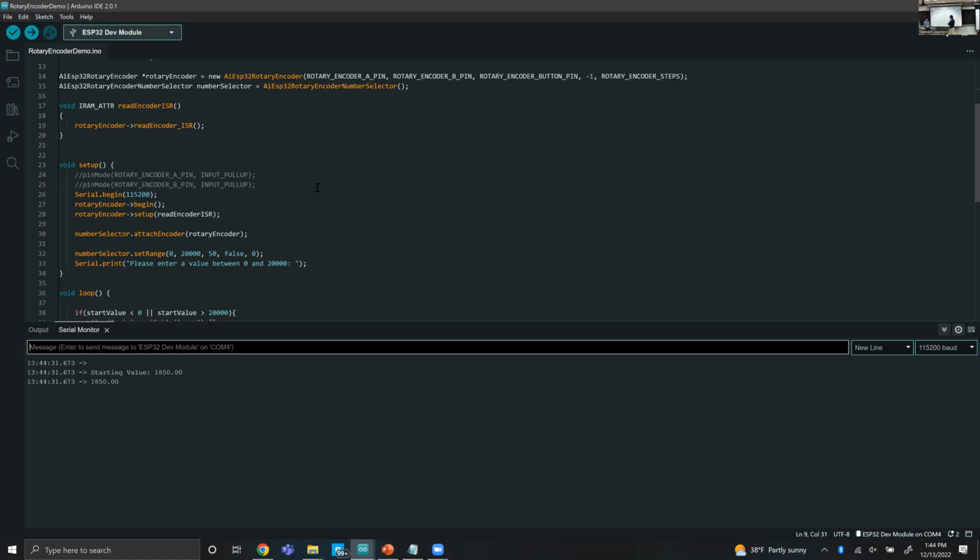I know, but I don't understand the 185. Let me change it. So that number, that's our set RPM, right? So now you're changing the RPM. This is what we're gonna send out to the motor ESC. So you have steps, so it's almost like a feedback control type thing, right?